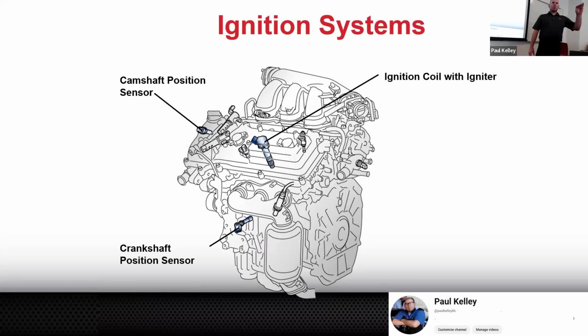So the little summary was the misfire was here. The coil went here, it didn't fire. So she determined it would have to be the spark plug. I said, well, it could be, but there's other things it could be. And then she said there's a check engine light, and the DTC was for primary ignition circuit voltage. So at that point, because I understand the system, which is where I want you to be, I'd be like, hold up, you're going after the spark plug?